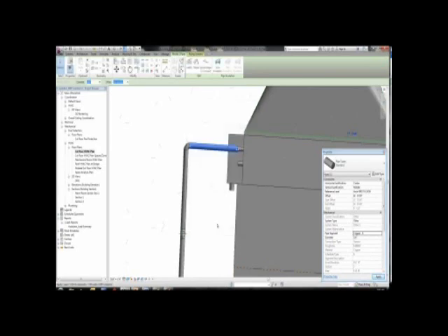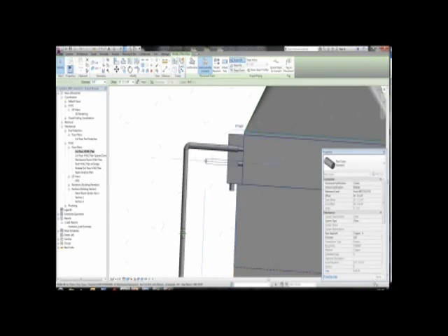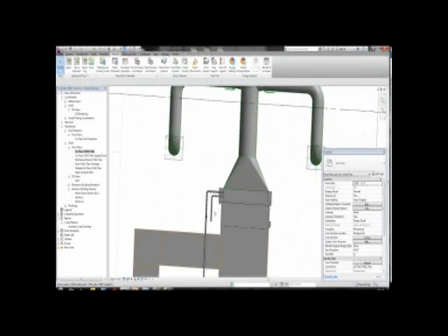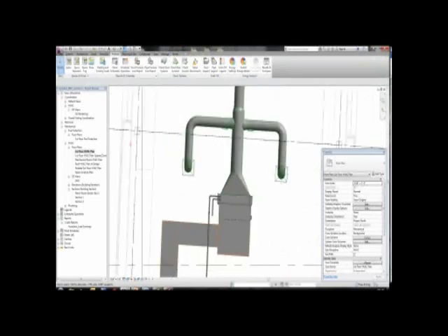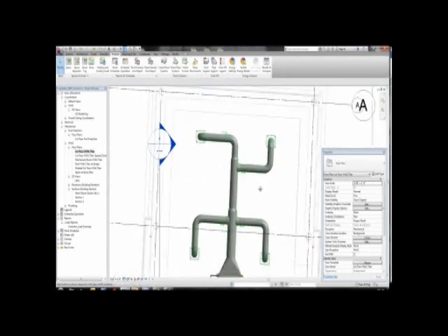So now that I have that created, I can select the fan coil unit, right-clicking on the connector and choosing draw pipe. And now you can see up in the options bar, it's giving me that 5/8 of an inch size as desired with all of the settings. And again, being accessed through type properties. And there's my 5/8 inch setting up in the options bar for copper K. So let me zoom out. I'm just going to pan over here to the top of the duct system.